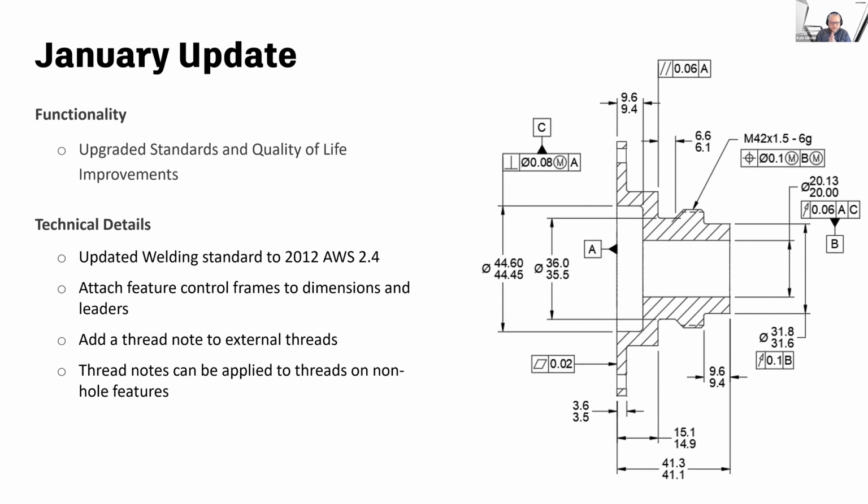And again, you would need to consult a GD&T expert in this, or the ASME Y14.5, I believe is the ASME version. I can't remember what the ISO version is that does something similar. Yeah, again, thanks, Chris. GD&T is geometric dimensioning and tolerancing. So that's what that is. M is the maximum material condition. You'll also see L, which is least material condition, and there's a couple others.